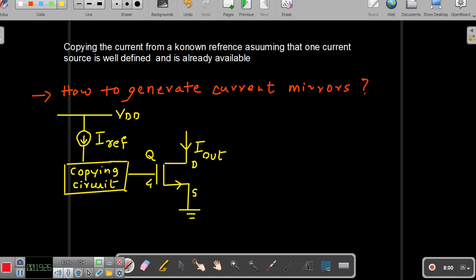So now when I know that I have got a standard reference current here, right, and if I make the output current as a function of this reference current, then whatever the external parameters, could it be the supply, could it be the process, could it be the temperature, they are not going to influence the output current, and your output current becomes independent of all these things. Which is the necessity in operating the MOS based devices, right? So now we will try to see how exactly we are able to do this. So now for a MOSFET, you can write these things.